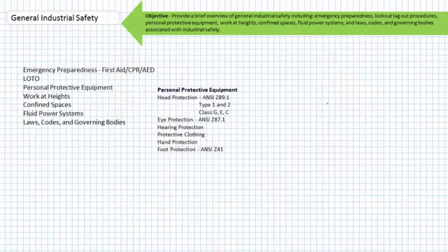Common hazards to the eyes in an industrial environment might include airborne particles, pinhole leaks in pressurized systems, explosions, or other similarly undesirable circumstances. If you've ever used a pneumatic nail gun before and disconnected the hose under pressure without holding onto it, you are no doubt aware of the phenomenon known as hose whip. Where does the heavy metal coupling go? It shoots straight into your eye. This is true no matter how vigorously you zag or zig. Put some safety glasses between you and that hose and hold onto it when you disconnect it.